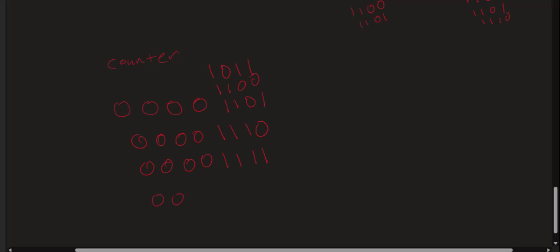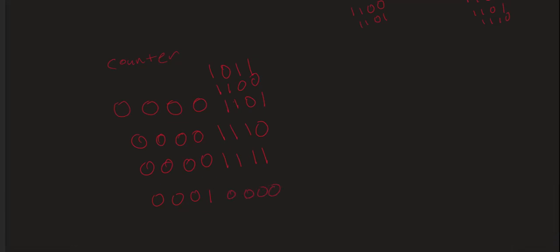Okay, so when you get to this stage, the way the output carry works is it's the AND of all of these. So the AND of all of these enables this counter over here to start counting. And so then it will count to 1. These will roll over to 0. And then this one's not enabled anymore.